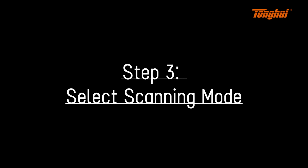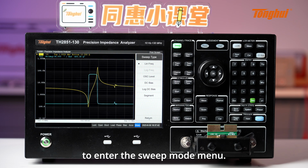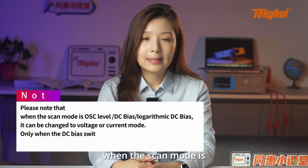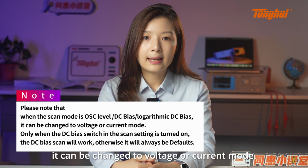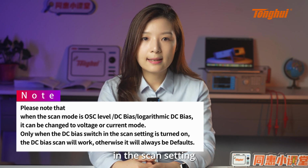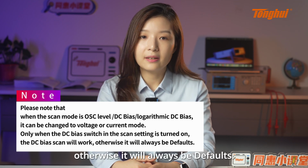Step 3. Select Scanning Mode. Press Sweep Type on the front panel to enter the Sweep Mode menu. Press the corresponding button to select the sweep mode: linear frequency, logarithmic frequency, OSC level, DC bias, logarithmic DC bias, segmented sweep. Please note that when the scan mode is OSC level, DC bias, or logarithmic DC bias, it can be changed to voltage or current mode. Only when the DC bias switch in the scan setting is turned on, the DC bias scan will work. Otherwise, it will always be default.